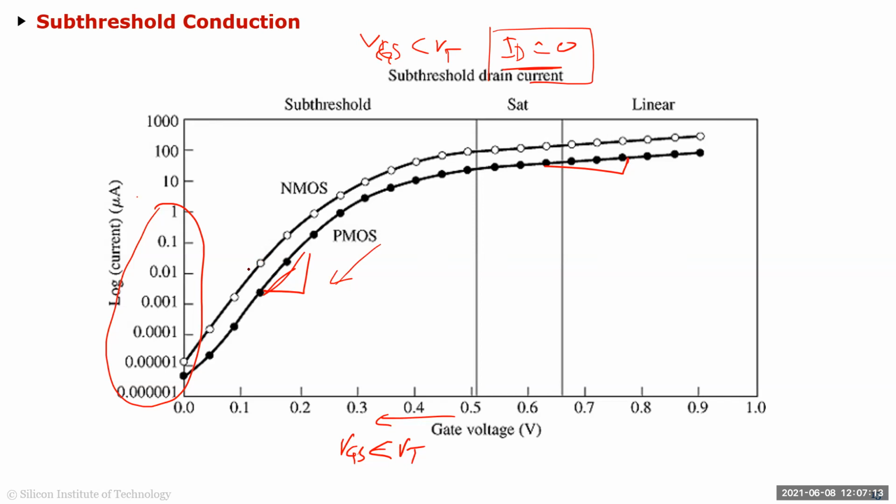If it is low frequency. If it's high frequency, it's a different deal. But unfortunately, a lot of the designers, still old designers like me, they still hold that fear, not in the sense that I use subthreshold, but a lot of designers who have been designing for a while, they still think, no, I'm not going to design in the subthreshold because the models are bad. But they're not bad. Now the models are really good. So you can design in subthreshold now if you're using BSIM4, and when your chip comes back, it'll be very accurate. Obviously, the foundry has to do the job of making sure that they are giving you the right fitting parameters.